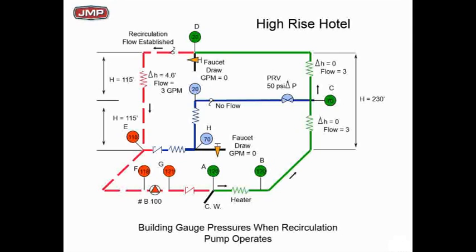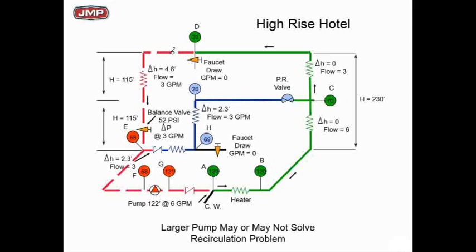And I hope you see from a physical engineering standpoint that 70 pounds of pressure is not going to flow in the 118. So how would you fix the problem? We've got to fix it quickly. So as you see here, I'm just changing back and forth between the slides so you understand the point. You see where the problem is there. I'm going to add a circuit setter or a balancing valve on that return line coming from the top 10 floors. I'm going to take a huge pressure drop across.